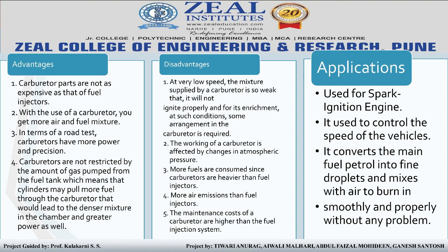Disadvantages. At a very low speed, the mixture supplied by a carburetor is so weak that it will not ignite properly, and for its enrichment in such conditions, some arrangement in the carburetor is required.